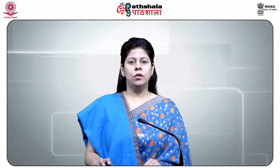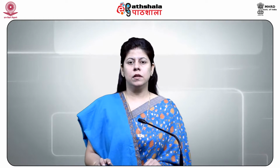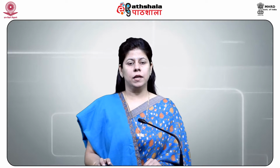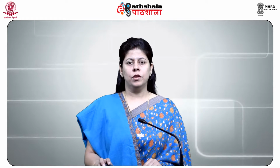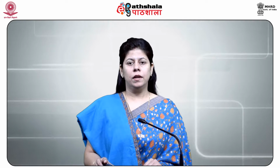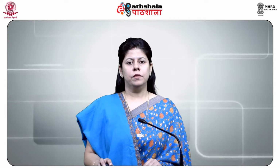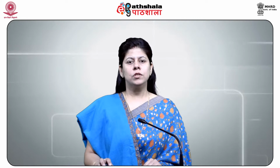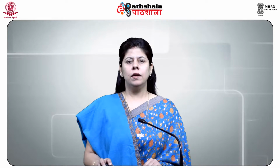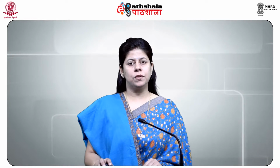Now let us see non-dispersive X-ray absorption method. In this apparatus, a tungsten X-ray tube is employed as a source which operates at 15 to 45 kilovolt. A synchronous motor driven chopper and an attenuator are placed between source and sample reference compartments, which alternately interrupt one half of X-ray beams. There are duplicate reference and sample cells up to 65 cm in length.